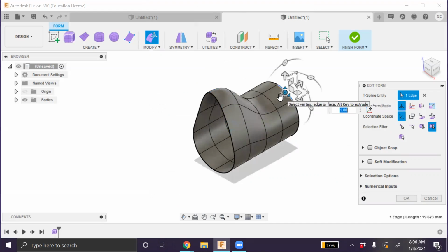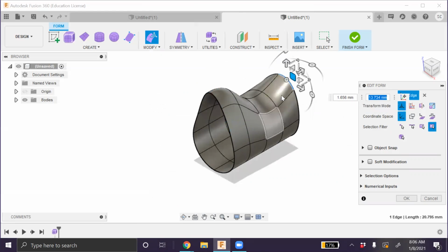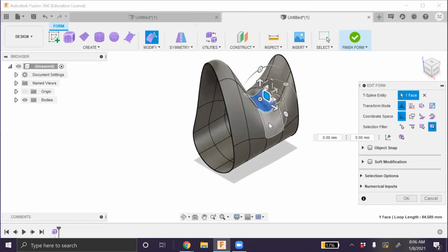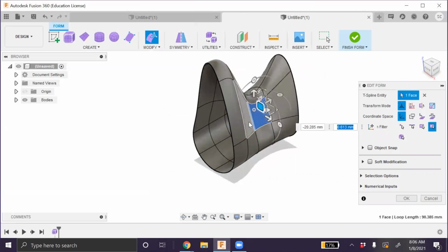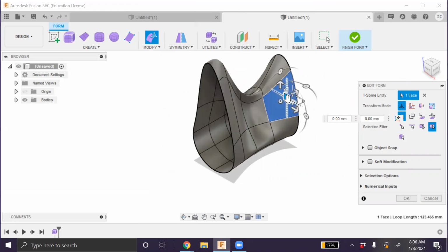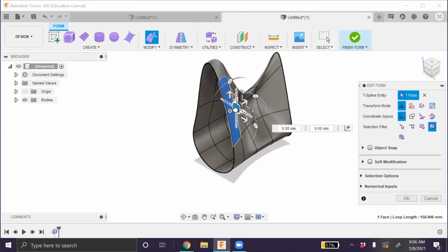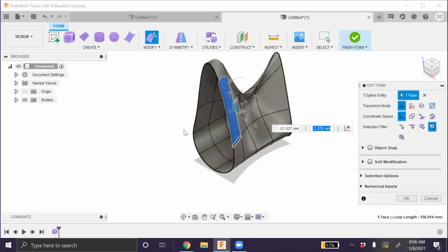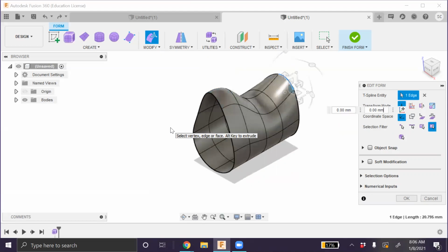If you are looking to modify something, say just an artistic piece like this, creating these dents, creating this kind of an oblique shape without freeform modeling might mean hours of making basic shapes and then giving loft commands and then figuring out interfaces between each curve and how you join them. With freeform modeling, I just had to figure out which surface had a basic shape, and then I went about giving it that kind of a geometry.